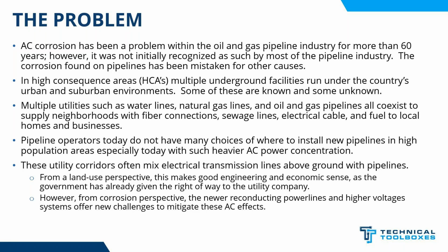Pipeline operators today do not have many choices to install new pipelines in separate right-of-ways. And even if they did, it would soon be filled with other utilities, particularly AC power. And then the thing we need to think about is the mix of these and how they affect each other. We can't do anything about it now. From a land perspective, it makes good engineering and economic sense. However, from a corrosion perspective, it's not a cool thing.